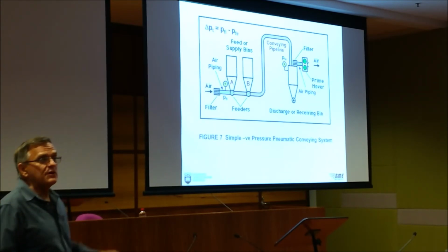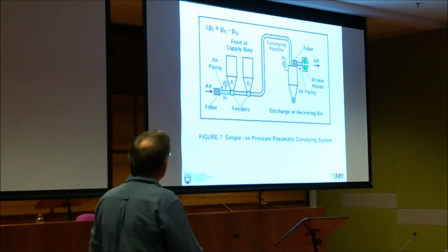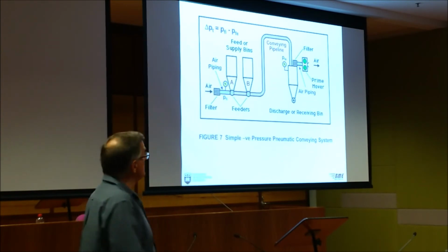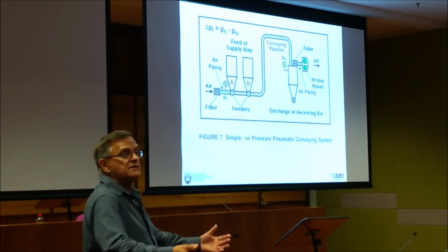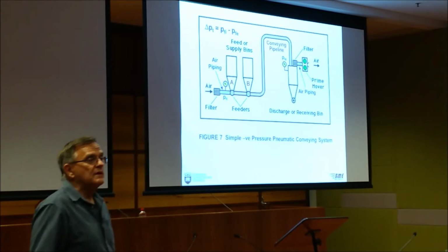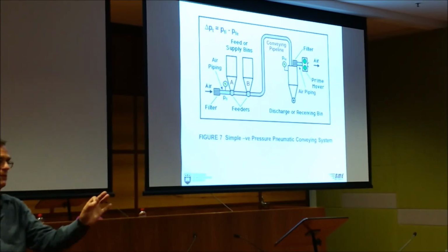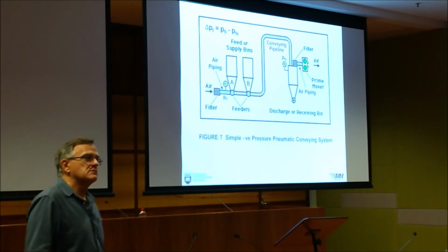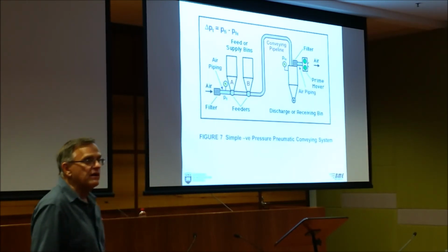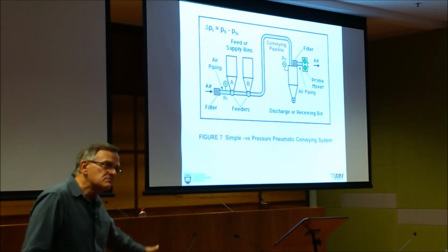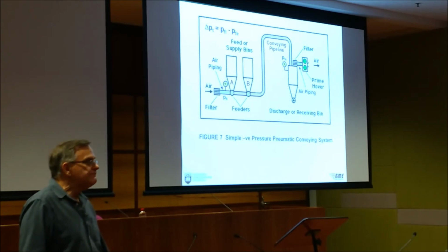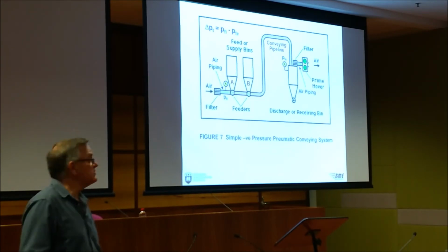Right, pressure drop, we use the same equation. The pressure drop across that pipeline is PFI minus PFE. So PFE might be -20. So 0 minus -20 is 20. So delta PT is 20 kPa. So when you talk about pressure difference, it's just kilopascals. You talk about a static pressure, you talk about gauge units. Kilopascal gauge. Doesn't matter whether you're talking about pneumatic conveying or pneumatic circuits or hydraulic systems, you use the same language. Alright? It's not just pneumatic conveying, it's other applications of that.